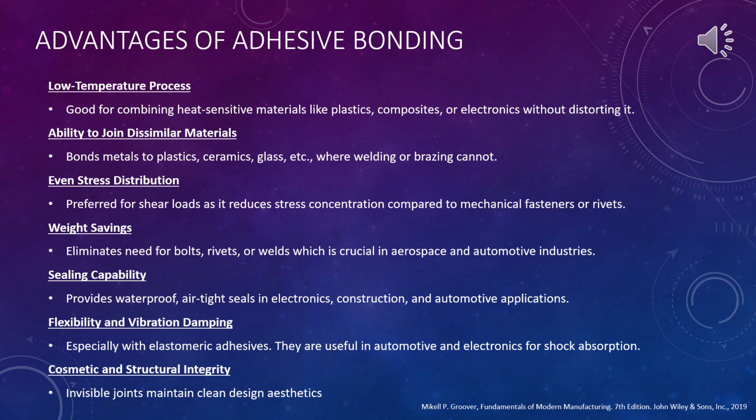Number 2 is the ability to join dissimilar materials. Adhesives are very versatile when it comes to bonding different types of materials, like metal to plastic, ceramic to glass, or composite to wood. This is very useful in the automotive, aerospace, and electronics industries, where hybrid materials are very common and traditional joining methods like welding or brazing do not work.